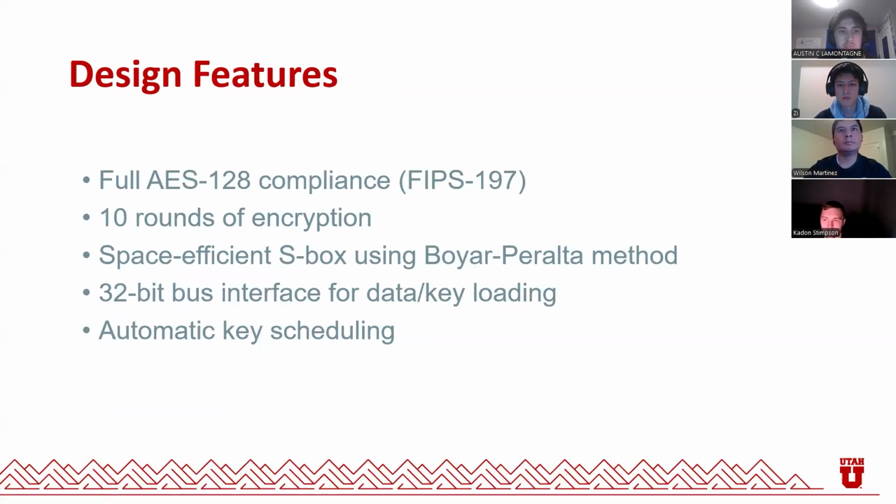And so our design features include the AES, which is fully 128-bit compliant according to FIPS 197. And then we have 10 rounds of encryption. So inside the AES round, we do 4 steps times 10 different rounds. That's according to the standard, just 10 rounds of encryption, which makes it almost impossible to crack.